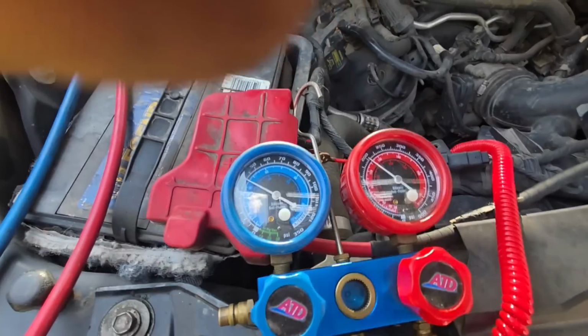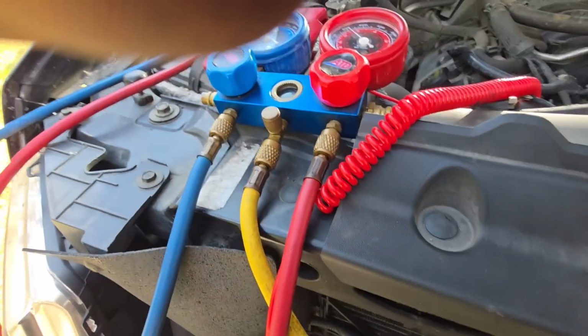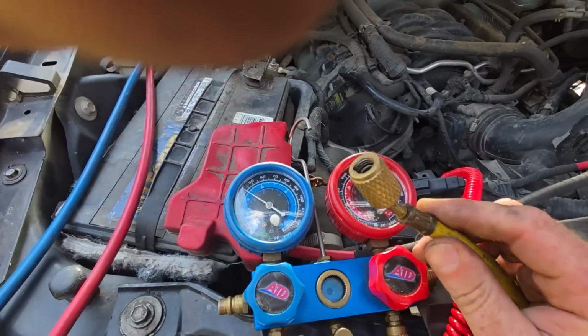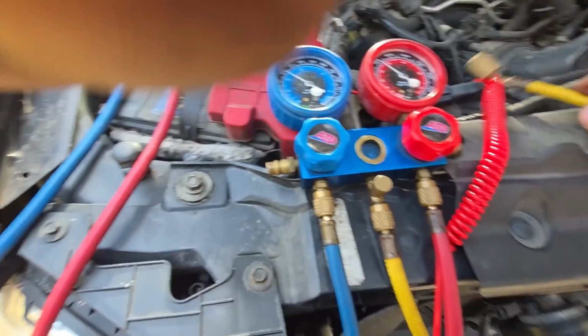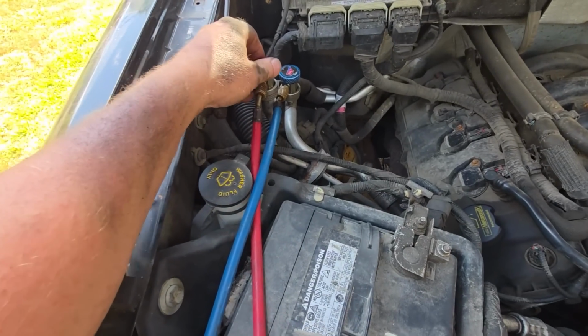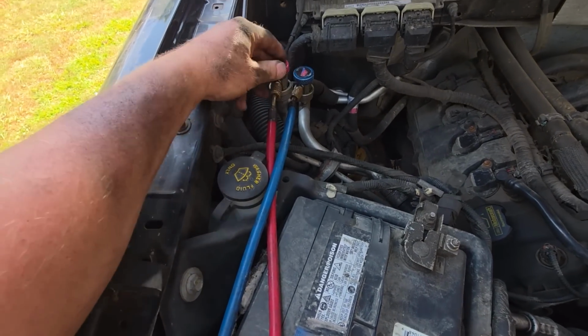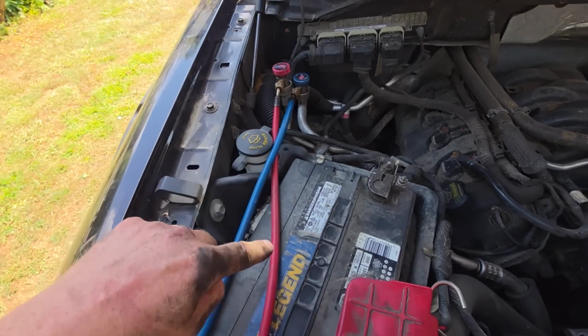I've shown this many times. Let's get this high pressure out of my gauge. It's very important when you do this step that you have a check valve on the end of your yellow hose. So what we want to do first, isolate the high side. So when I unwind this, that closes the Schrader. I no longer have high pressure going into this red hose.